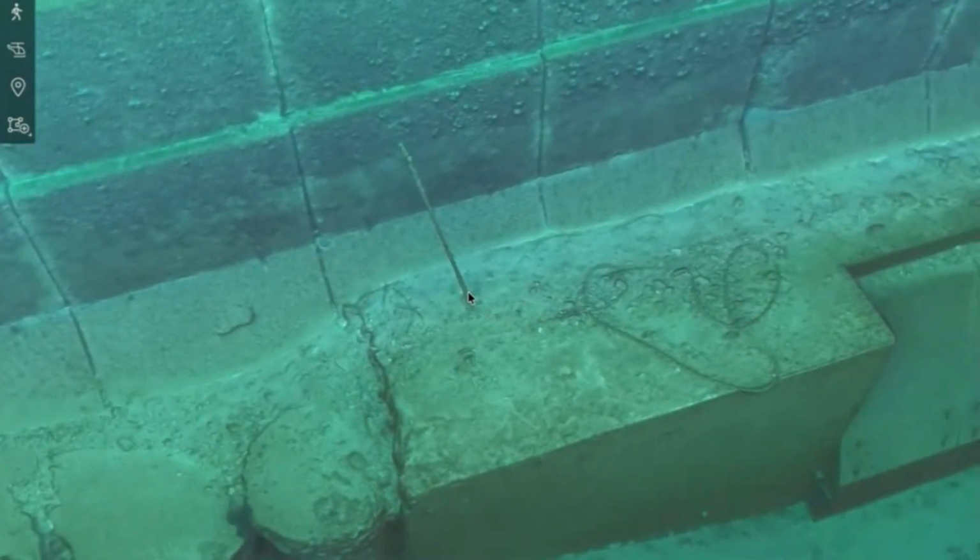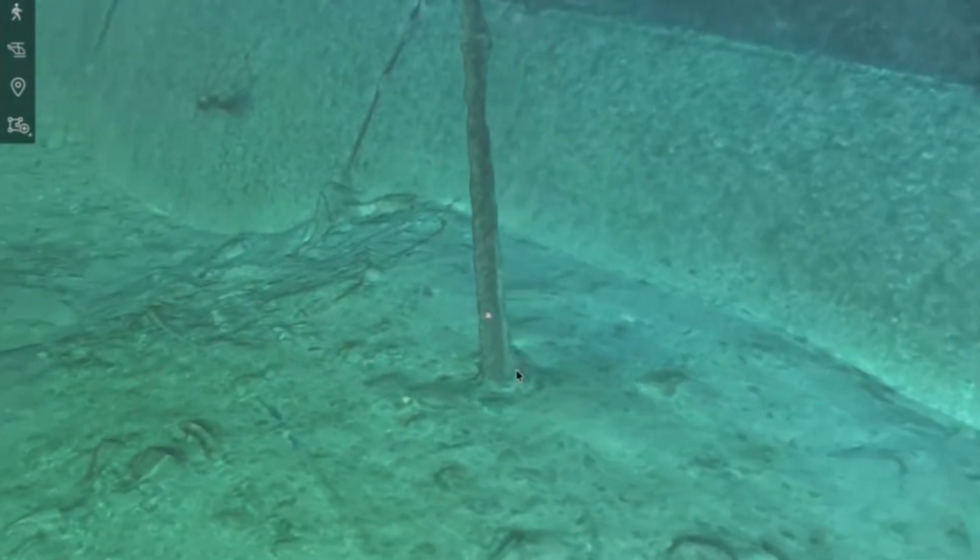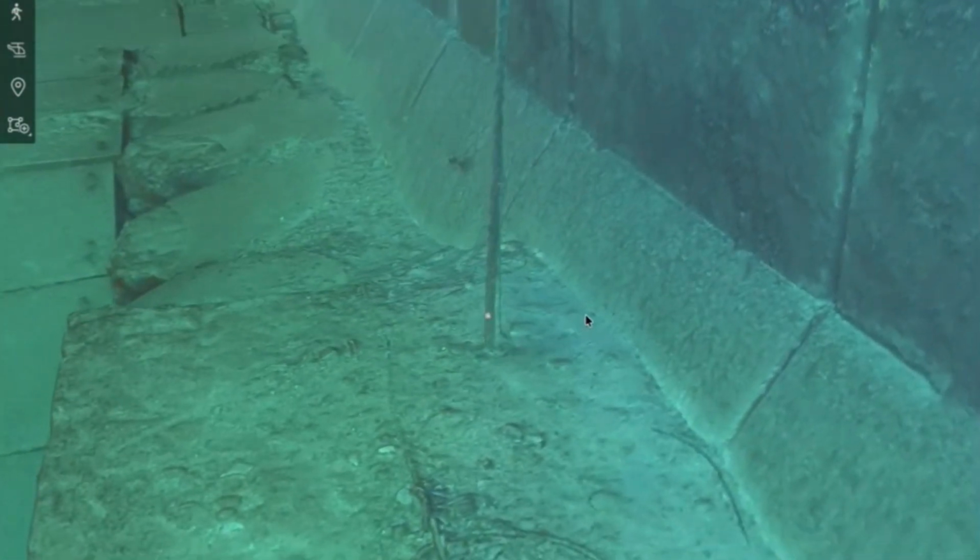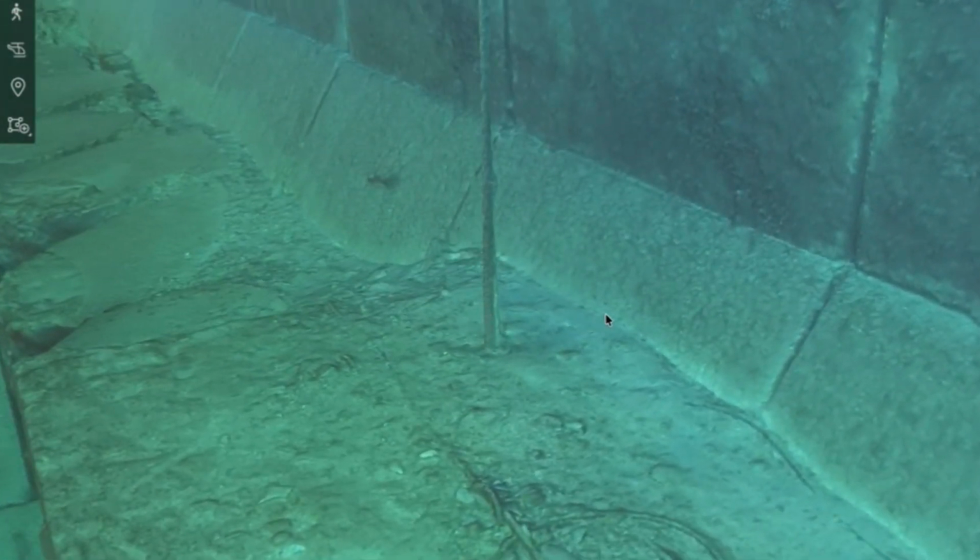So what does the hardware do? Why do we call it multibeam? Multibeam has an array. Maybe I can connect you on some other podcasts with the great guys who are working with multibeam. It has an array of ultrasound that comes from one point, let me say a small area. It is a beacon. And from the beacon, in most cases, you have 1024 beams that are like laser beams, but they are ultrasound, and they come back from something they hit.